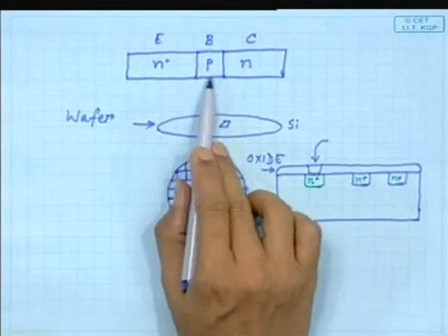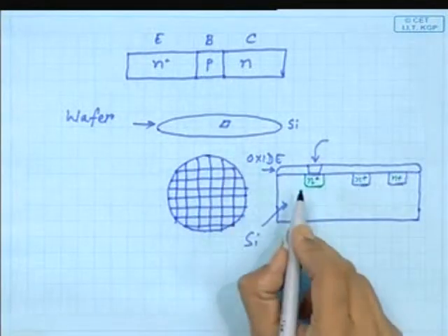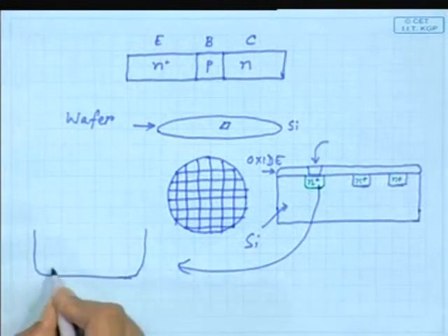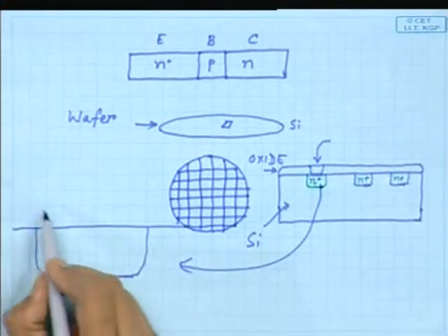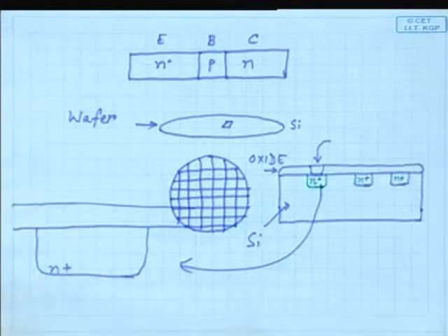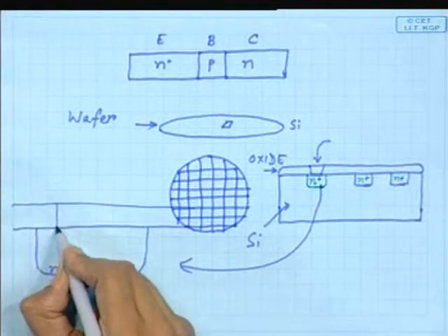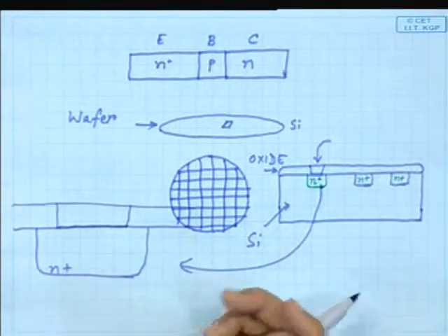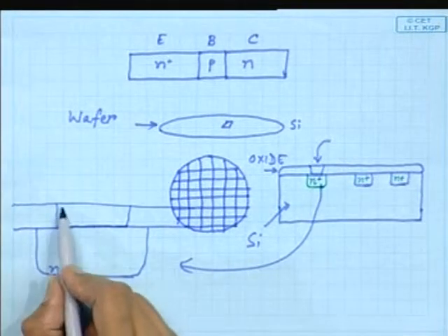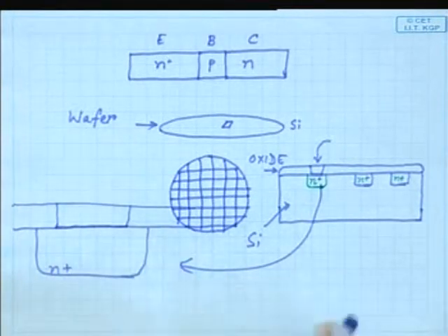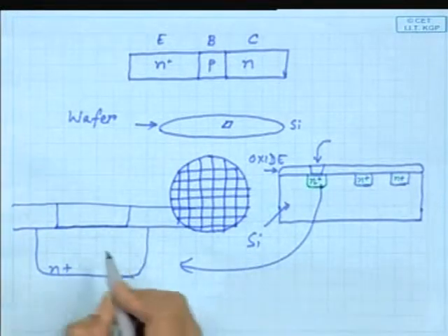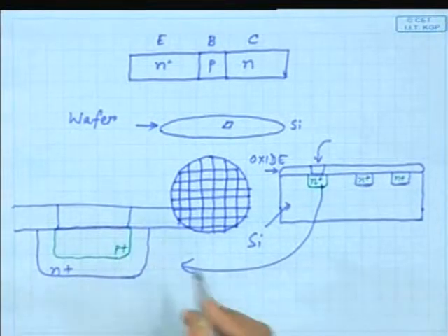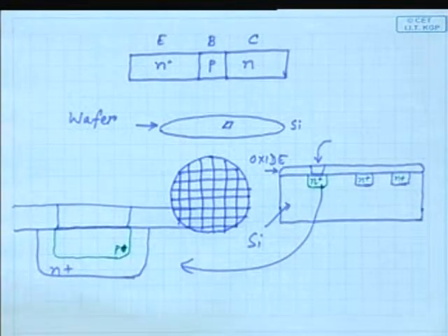Now, you need to have some sort of P region. Okay. So, within this, once again I can exaggerate this one. Suppose this is the N island you have made, and once again you cover it up with silicon dioxide, then expose some of the part, once again open a window. I think you know hydrofluoric acid or some such material can etch out silicon dioxide. So in the same way, you can etch out a window, expose that to some p-type dopant, and then you can form some p-type structure over here, not p plus, p-type material you can diffuse.